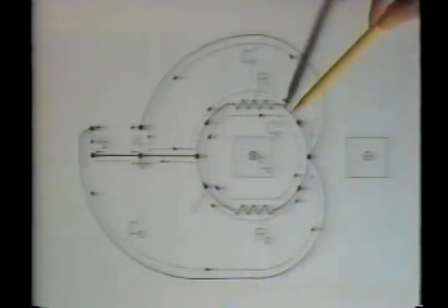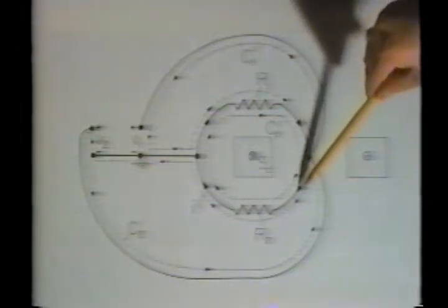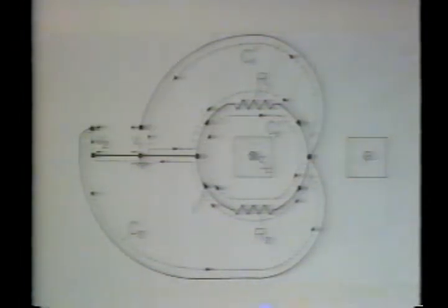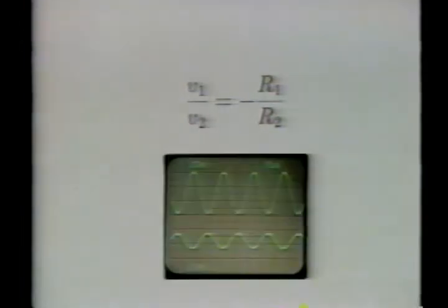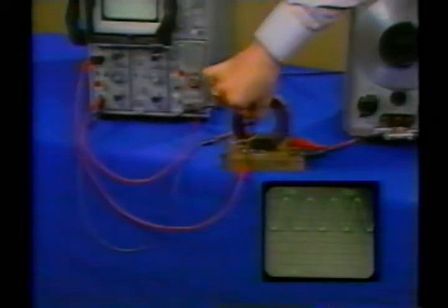If the probe leads follow the same paths, the signals should be the same. If we remove one of the leads and then connect the other one to its own ground, after having looped the lead through the core, what we see is this. Just as the series resistors form the secondary of a transformer, so now the lead itself is a one-turn secondary. The measured voltage is simply the time rate of change of the flux through the core.